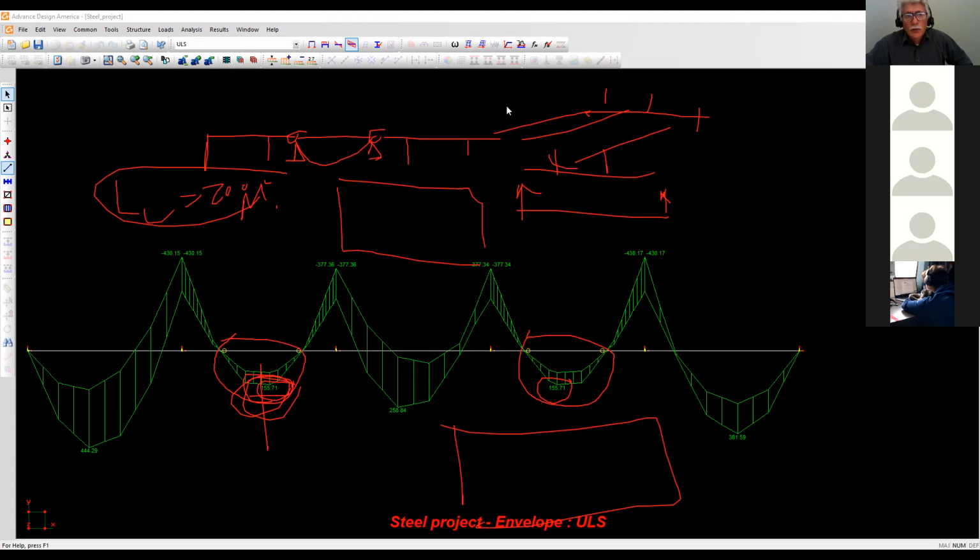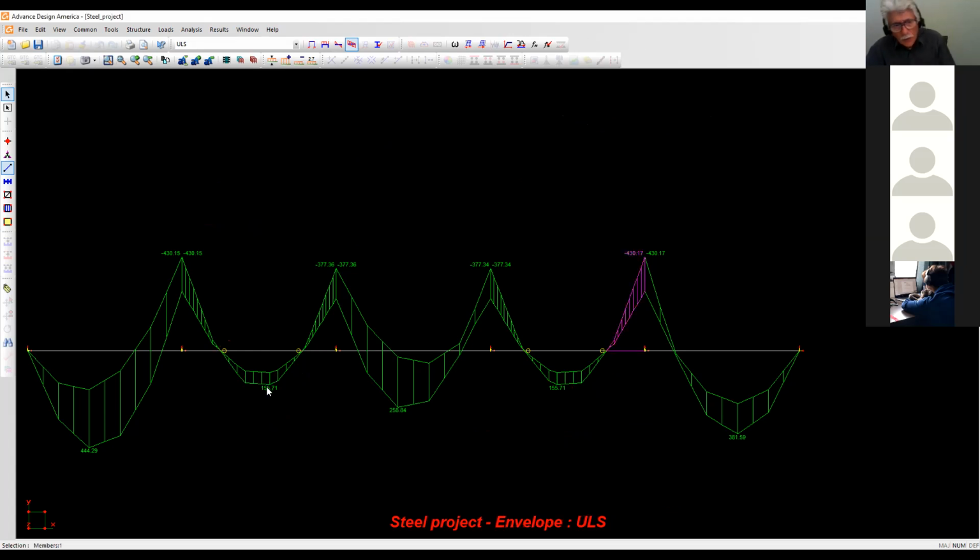When it comes to deflection, you put that right size beam into your model here. Like here, I told you, you put the right size beam in here. And now you notice that the moments have changed slightly from before. I don't know if you guys can see this, but they've changed slightly. Why? Because the beams are a little bit lighter. If I want to be really religious, I should go back and take these values from here, put them back in my Excel spreadsheet, and I'm only going to get better results than before. But I won't do that.